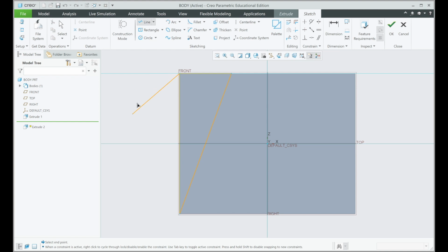Now we're always left with a little tail when you're drawing. So to get rid of that tail, you press the scroll wheel, and that will stop the drawing. Like that, and we use the select tool again, or we can go straight to dimension. So I'll click on dimension because I'm happy that it's selected, and you'll notice I've got one dimension appeared, which is an angle. That angle needs to be changed to 10. So I've just typed into it, and I'm going to type in 10.